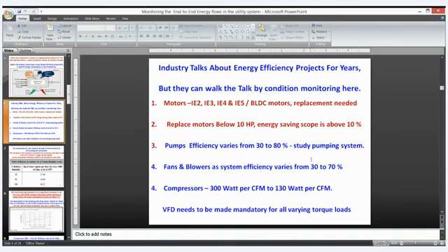See, for many of the motors, right from 2018 it has been told to change to IE2 motors, but IE3, IE4 and IE5 motors are there, and many of the industries have already changed. The large group industries have started changing that. Even with EC motors, you find so much appreciable savings. So let us try to analyze what the loss is in our existing motors, and then plan for the replacement of the motors.